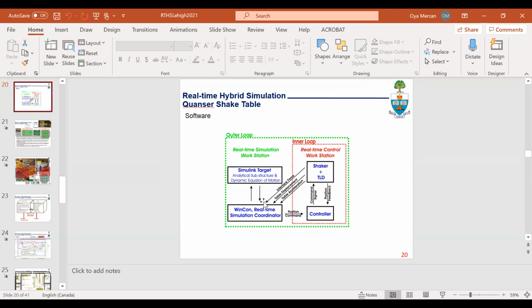But if you are developing it, the controller is quite challenging for the servo hydraulic system, as typically also the control platforms are not typically used for servo hydraulic system control, so you need to also handle some hardware challenges.